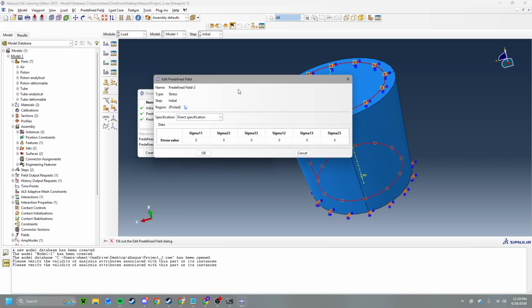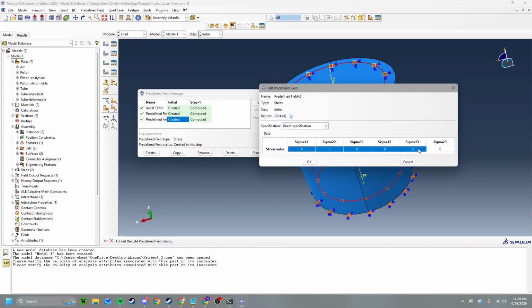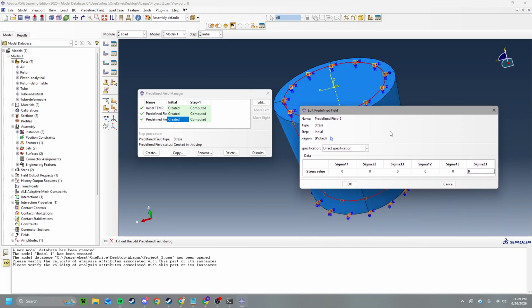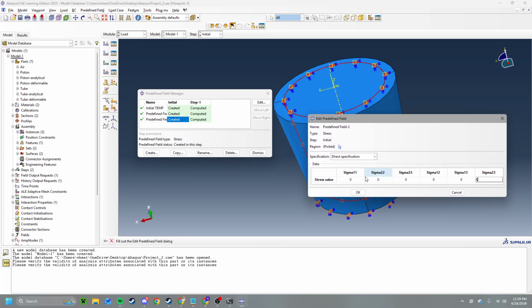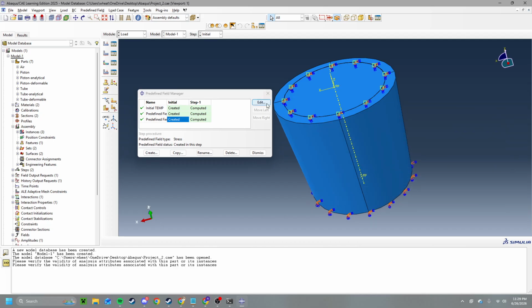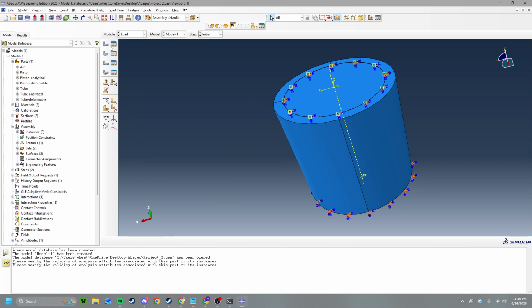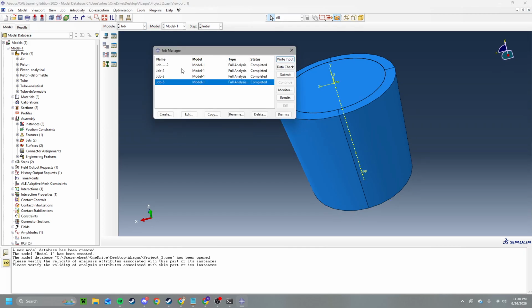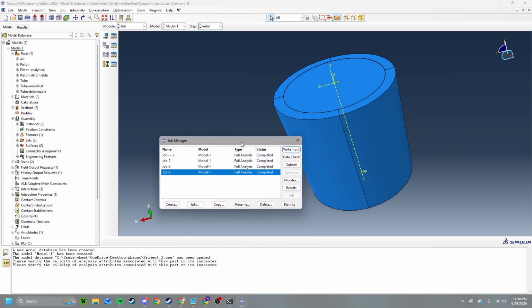And then we're setting our initial pressures/stresses throughout the Eulerian component. I'm setting them to 0 because it's starting at rest. And that's gauge pressure, so it's atmospheric pressure plus the reference pressure that we had earlier. So we have our mesh, then our job. There's nothing particularly special when you set up the job.